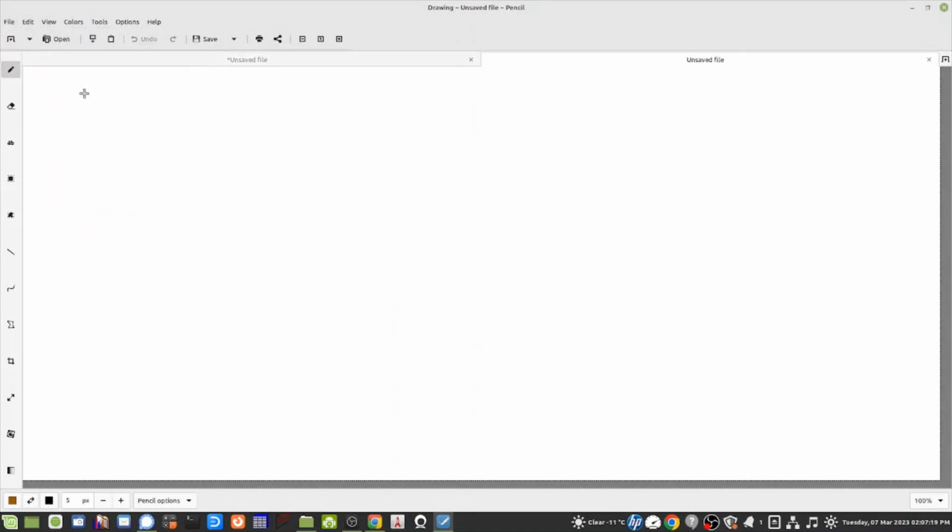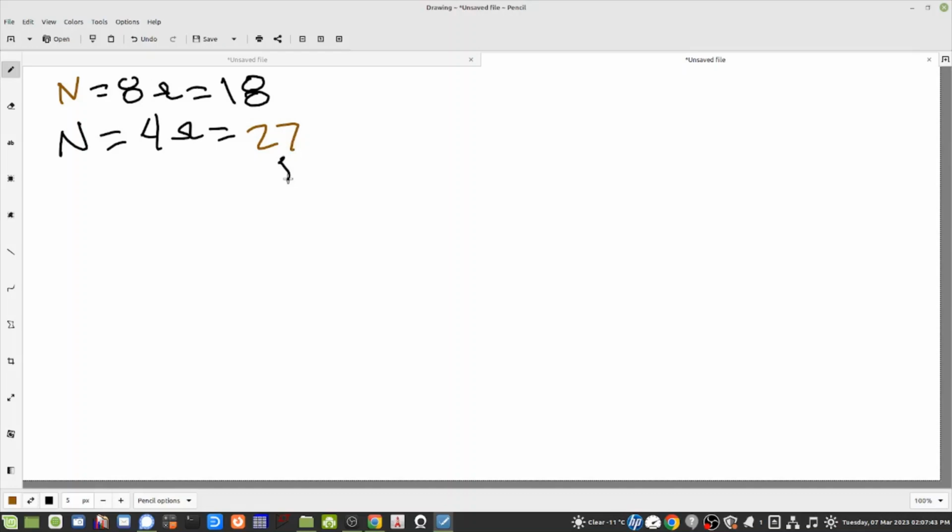Thank you. So the turns ratio for 8 ohms, we called it 18, but the turns ratio for the 4 ohm input was 27. Now I know that's going to be a problem right off the bat because they should be about the same. So let's introduce our transformer impedance formula, which is the meat of what we wanted.